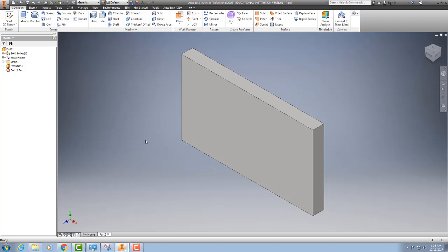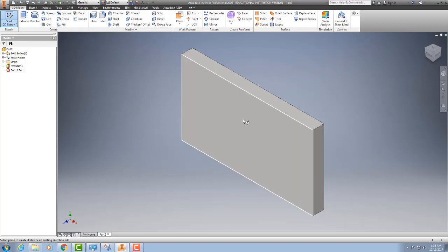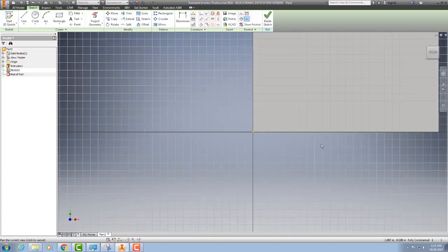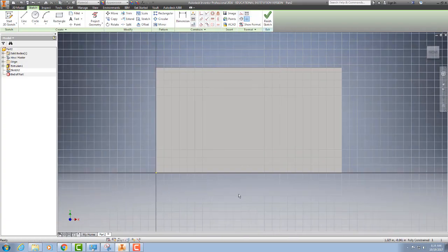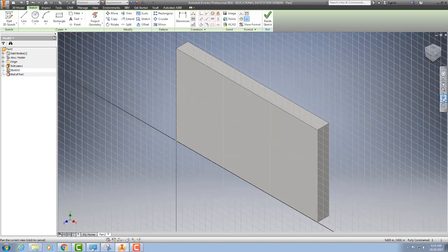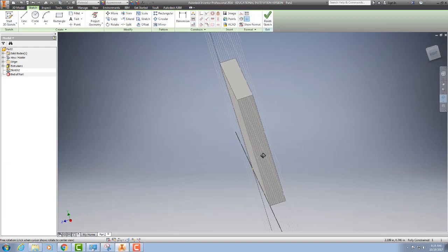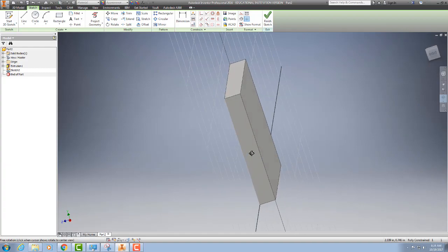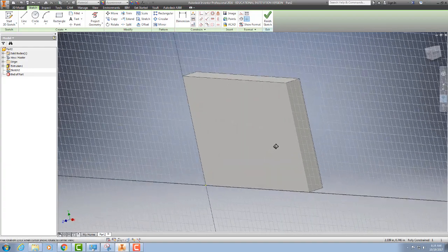This is where we're going to use two concepts, project geometry and the concept of locating and dimensioning a feature on a part. So I continue the loop by creating a sketch on this face, hold down the scroll wheel, move over in this direction here to center it. Now, I have a sketch plane that's on the face of this plate. It's kind of hard to see, but there you go. You can see that there's a sketch plane on that front face.